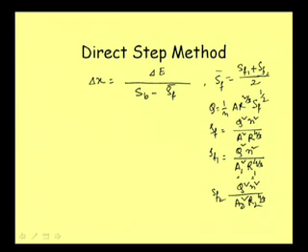Now, what does it indicate? If we want to calculate this delta x, we must know, similarly for the energy difference calculation, y1 plus v1 square by twice g, and the energy at section 2 will be y2 plus v2 square by twice g. So, we need information about a particular section.